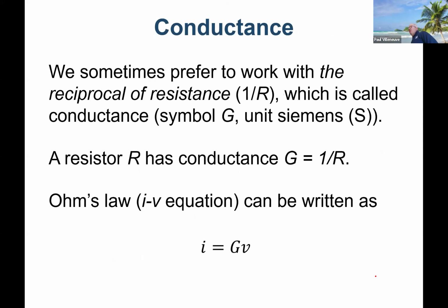Another term, and as you get more advanced in your analysis, you will use the term conductance way more because we actually live in a parallel world. And what I mean by that is the outlet over there is connected in parallel with the outlet over here, et cetera, et cetera. So most loads tend to be connected in parallel, so they'll have a constant voltage. So using conductance actually makes a lot of our calculations much, much easier.